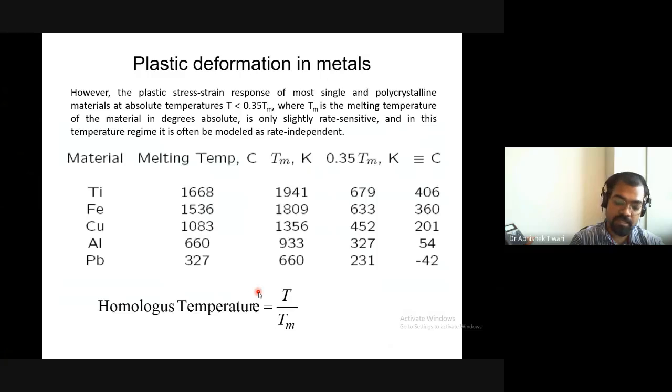If you remember, diffusion is a function of time as well as temperature. So what we have done is we have increased the temperature, and so the time dependence has been magnified. With time, the diffusion is happening at a faster rate, and therefore the flow of the material. For example, if a dislocation is locked at a Lomer-Cottrell barrier, this dislocation wants to climb. If climb is allowed, then this dislocation will cross the Lomer-Cottrell barrier, right?